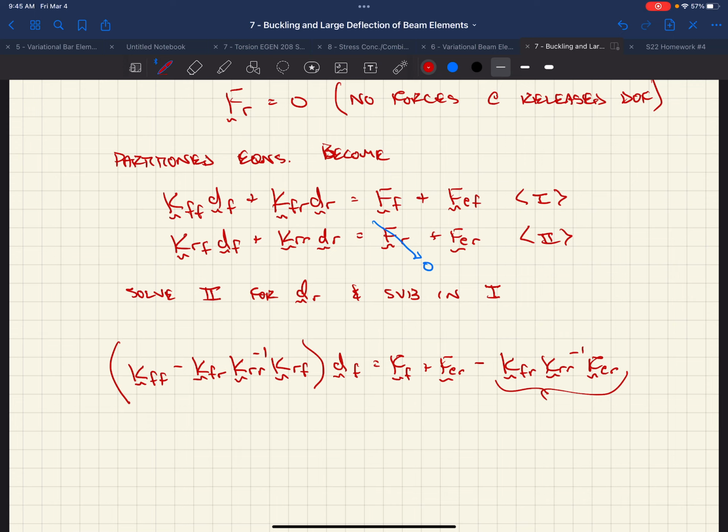So what does this do? Well, this takes those field loadings and brings them back to our nodal forces, taking into account the fact that we might not have moment transfer now, right? That changes the way that our beam behaves, right? If we can no longer have a moment force at the end of a beam, it's gonna make that beam go from thinking it's fixed, say, to fixed-pinned or something like that, right? So that's gonna change how we would distribute the forces that are acting within our element out to the nodes, right? What happened to FEF?